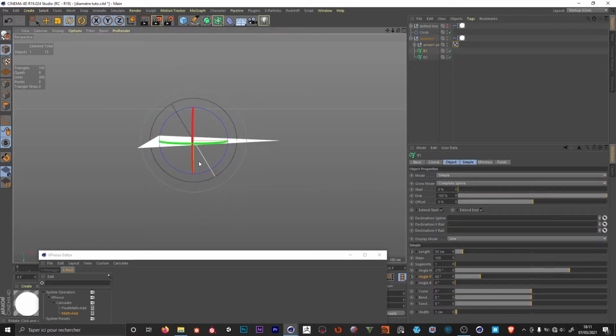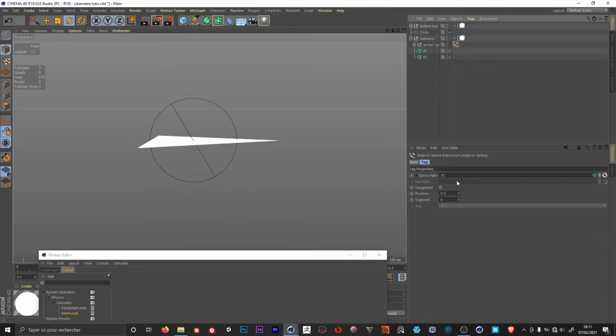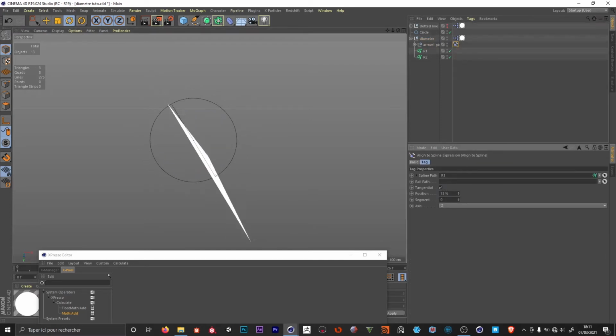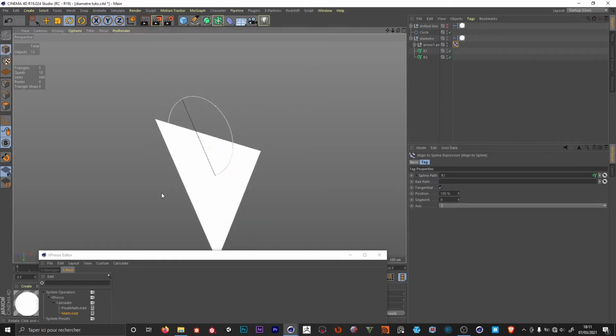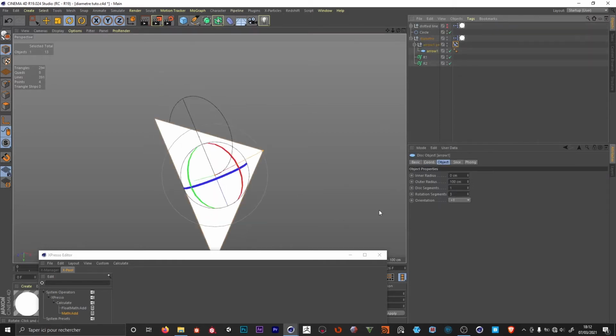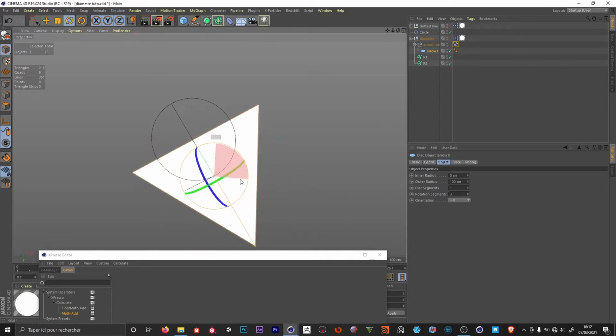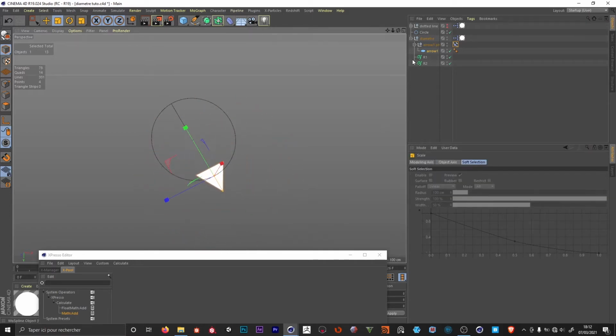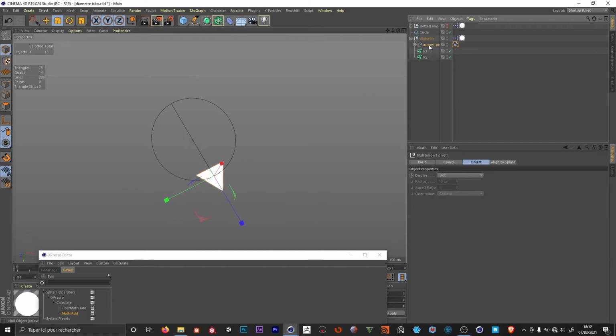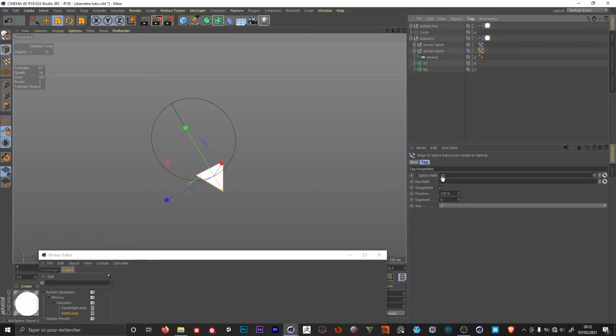So spline 1 is this one. We're gonna set this to be tangent, and we set the position to 100. We're gonna adjust the orientation. I rotate it like this. I'm gonna reduce the size. I'm gonna control drag, call it arrow 2 pivot. And I call the disk arrow 2. And this one is going to follow R2. So it's going to be on the other side.